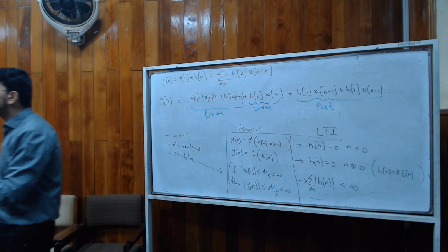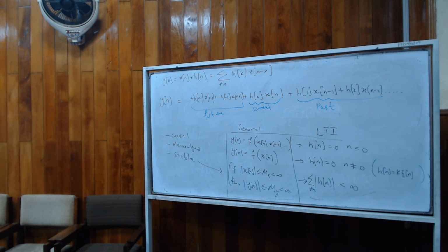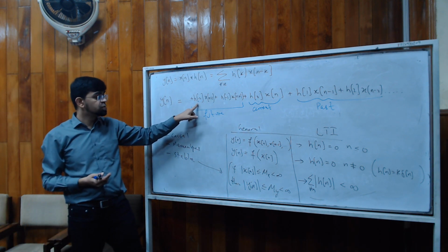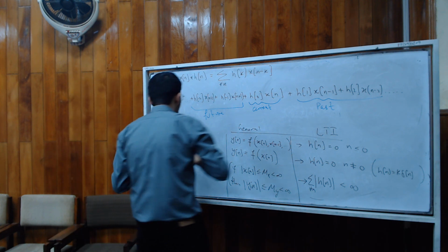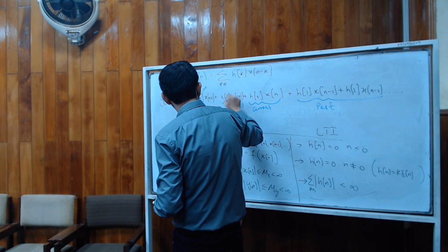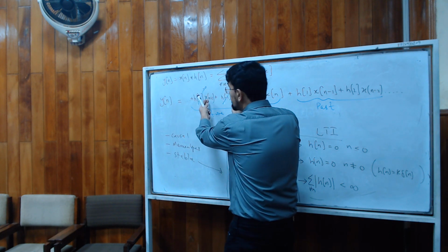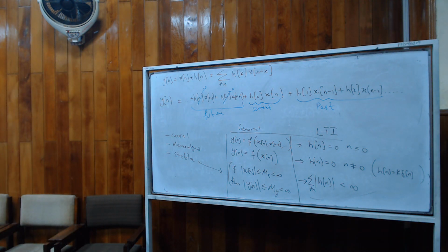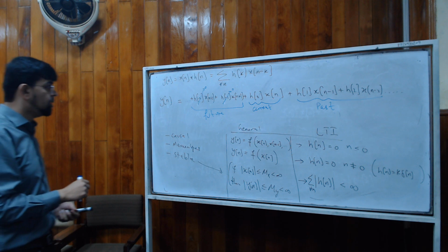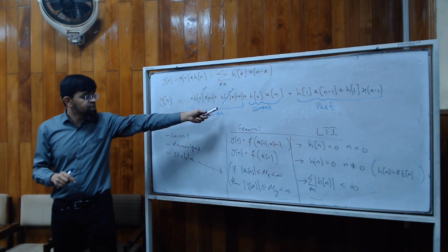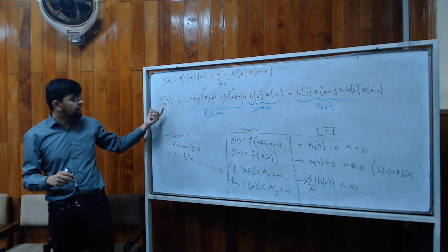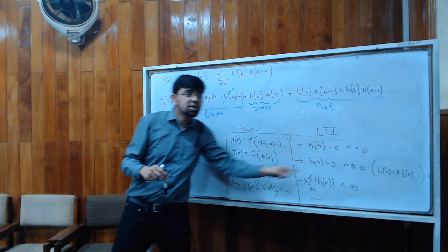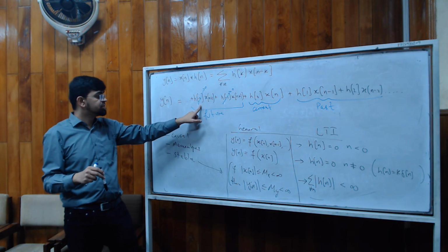So what you have in your control from a system point of view, the part of the system, are these impulse responses at -1, -2, and so on. If these happen to be 0, then all the future values disappear, and the output is not a function of any future values anymore. Because of that, we say an LTI system is causal if h[n] is 0 for n less than 0. So h[-1] is 0, h[-2] is 0.